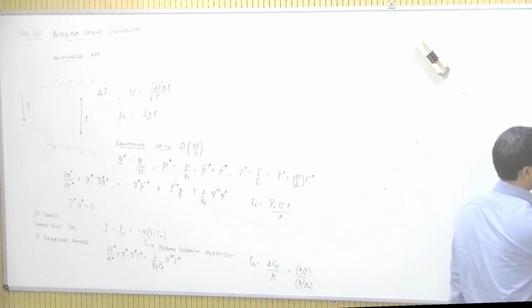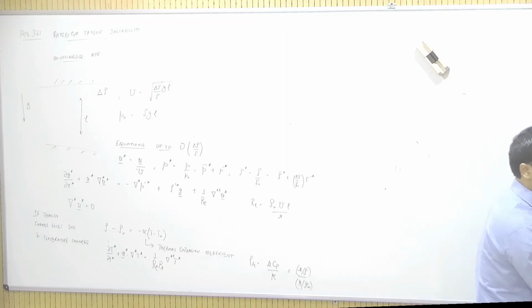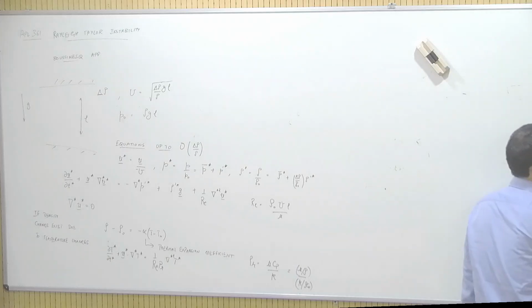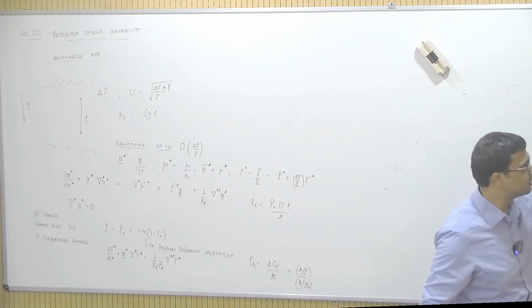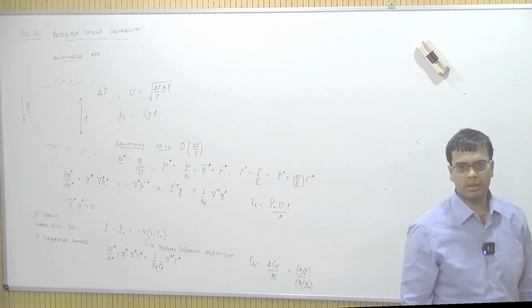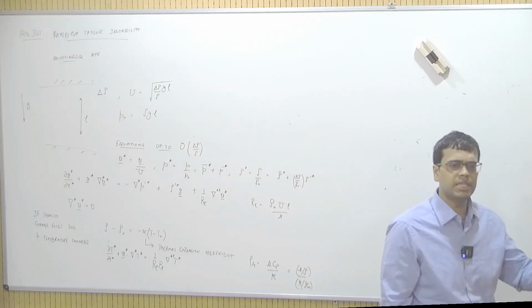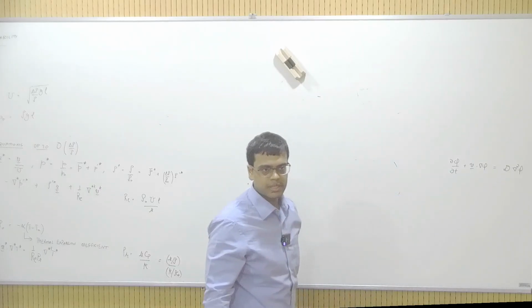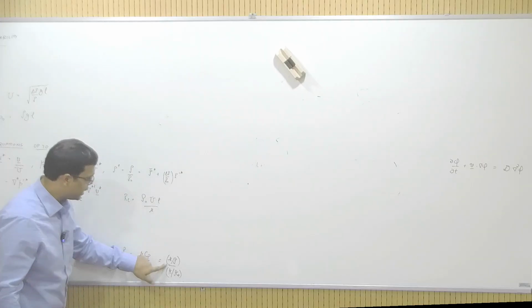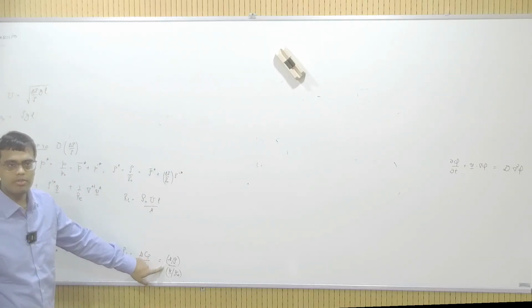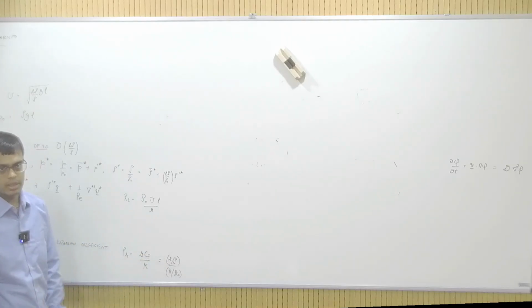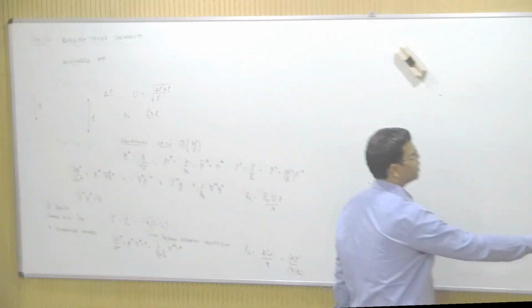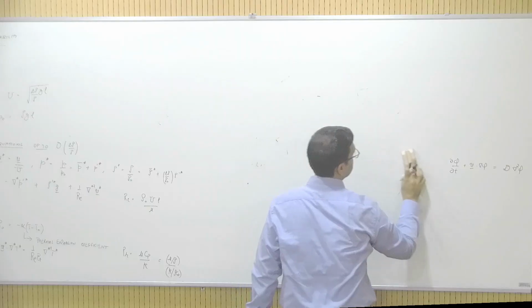If you have any variable, let's say phi in a fluid, that is a physical quantity which is diffusing, then we have seen that the units of this diffusivity, irrespective of what phi is, whether concentration, temperature, whatever, has to have units of meter square per second. So the Prandtl number is like a ratio of momentum diffusivity to temperature diffusivity. Every diffusivity has units of meter square per second.